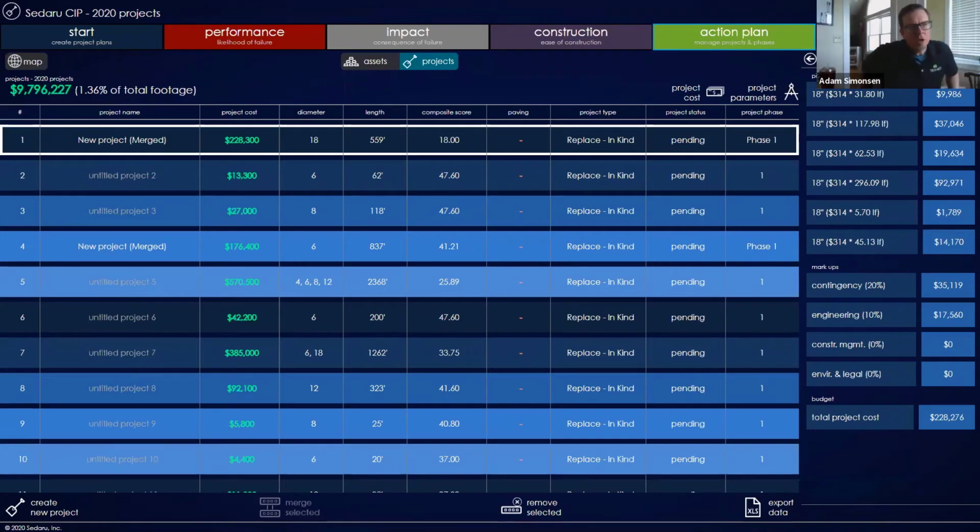So yep, absolutely. Let's hit one of the questions we have out here, Matt. The question is, how would you score CCTV data in here if we're talking about sewer systems? What's the approach there look like? Yeah, a lot of that data is still just essentially an integer or number or score, so it's treated the same way a lot of these other criteria are. You bring it in as one of those criteria and assign scoring, most likely 0, 1, 2, 3, 4, 5 for certain ranges of those scores, and include that in your LOF, most likely your LOF category.